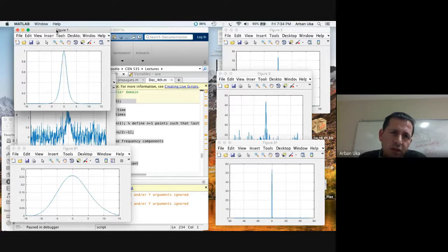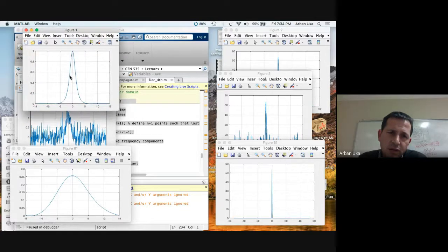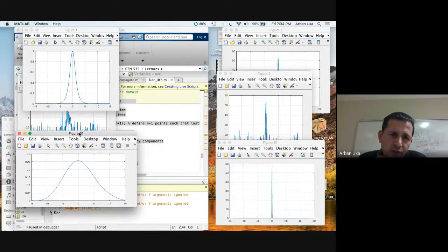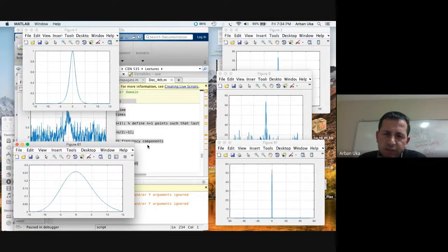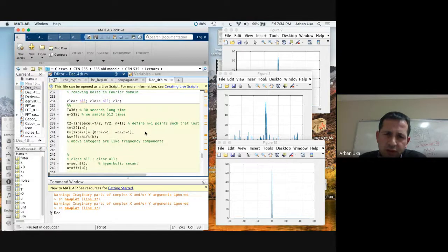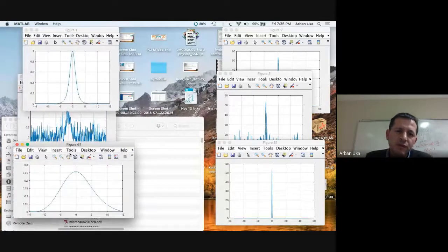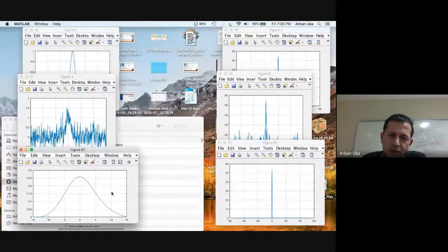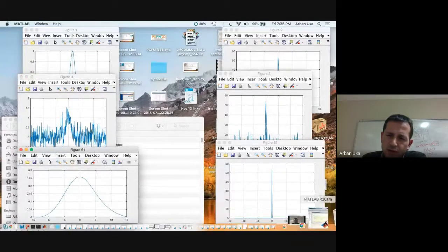If you look at the width here at the middle of this amplitude, it's plus minus 2, then this has jumped to plus minus 5. This is what we see here. From maybe plus minus 1 probably, to plus minus 5. And this was all done because we filtered very harsh. But what is interesting is that we have no noise. So all the high frequency terms, all the noise is gone. So this is how bad it was, but we could clean it out with notch filters.